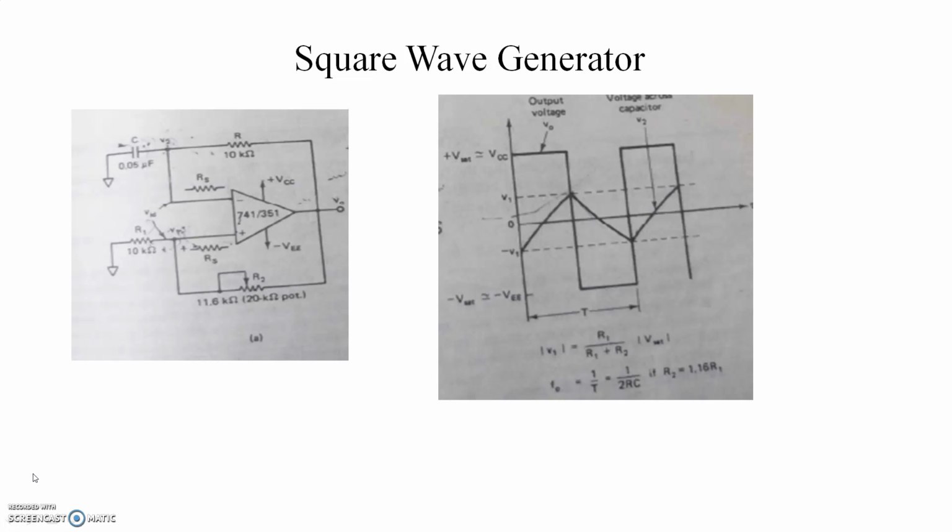That is, the voltage across the capacitor C in the feedback path is 0 at the moment the supplies are applied. This means that the voltage at the inverting terminal is 0, since the voltage at the capacitor appears at the inverting terminal.